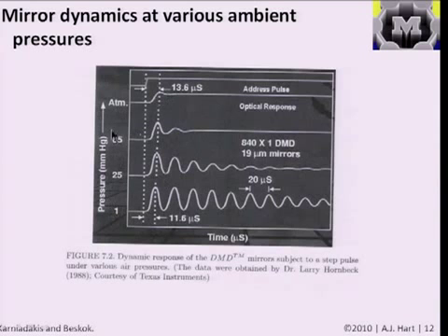And you can see that the damping provided by the gas flow is really important. And they showed that by having different experiments done at different gas pressures. And at the limit of, say, 1 millimeter of mercury, or about a 1/1000th of an atmosphere, there's a lot of ringing in the performance. And you can see it takes a long time for the mirror to settle out. This wouldn't be suitable for video.